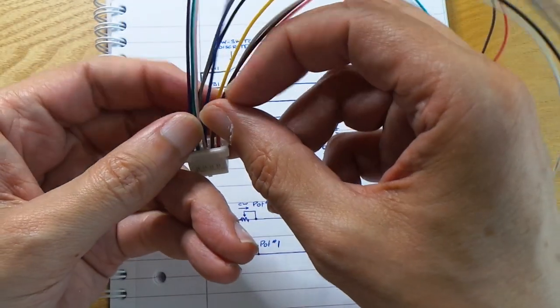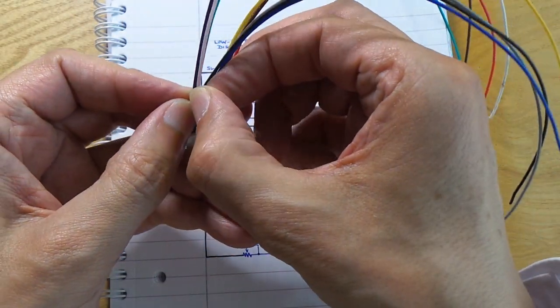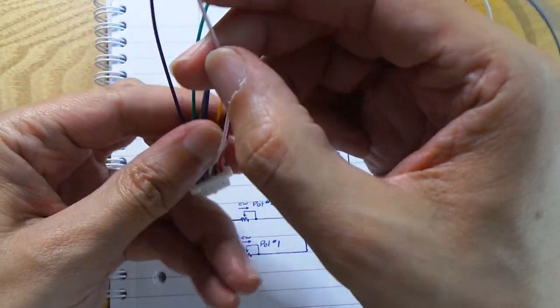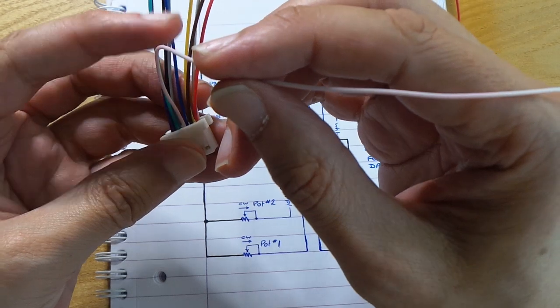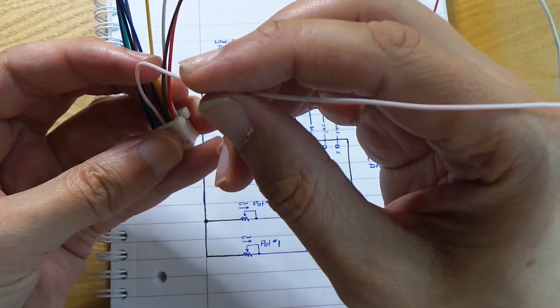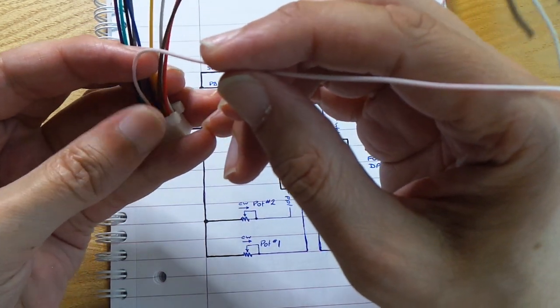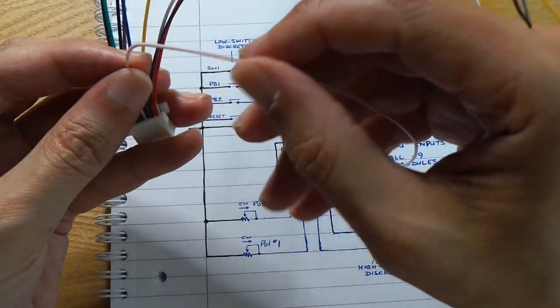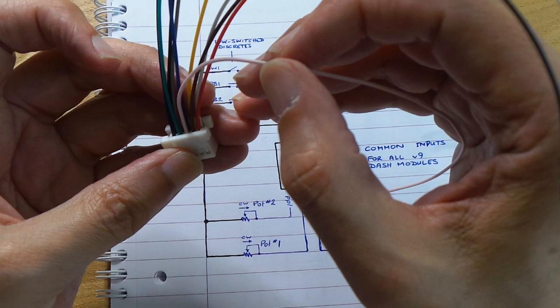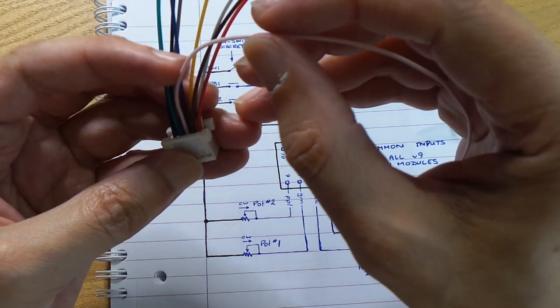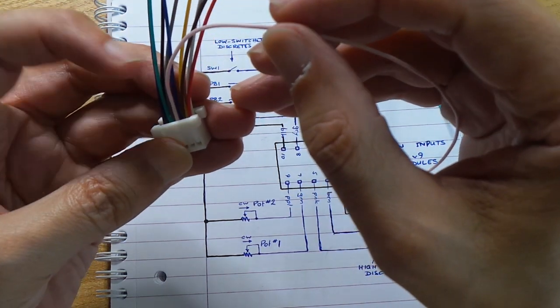Pin 5 is a pink wire, and that is connected to the secondary ignition power. Now the Firebird has 2 ignition sources. One is on the whole time when you switch the engine on, and that is what we call the primary ignition power. The secondary ignition power is another ignition signal which is cut out temporarily while you're cranking the engine, so that it's only driving the essential things for starting the engine.